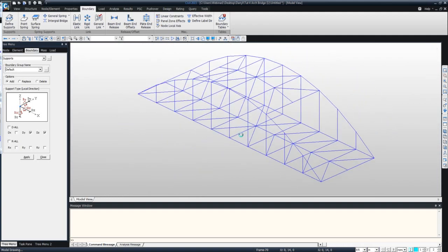And then let's go to these end nodes, and let's assign a set of boundaries for each of them as well. So let's go here. And let's say for this one over here, I want to restrict just the X and the Z direction. So we'll turn this off, we'll turn this on, Apply. And as you can see, the shading changes along the axis for each restriction.